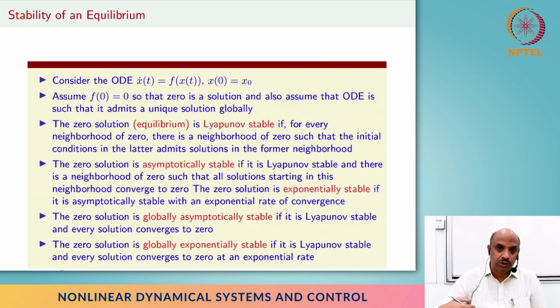What one can show through numerical methods is basically a demonstration. One can see that, okay, fine, I'm convinced that this is Lyapunov stable, and that is kind of demonstrated on a few initial conditions. So then where do we end up? How can one actually show a particular equilibrium point is Lyapunov stable? Well, one way of doing it is to solve it analytically. You'll have an expression in terms of time for the solution x of t, and then check this particular definition. You bring in these epsilons and deltas and things like that. It's going to be a mess, right?